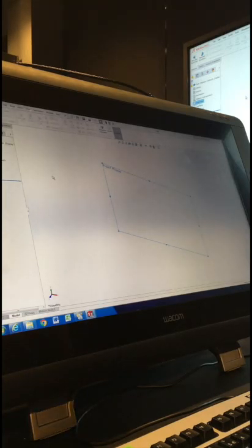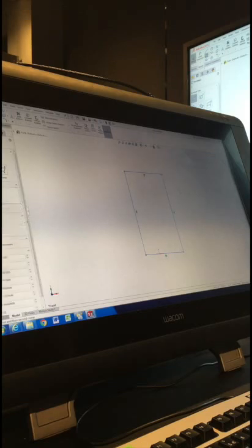So let's start this on the front plane. New sketch, front plane. And this is a new trick, this little one here. I'm going to start a rectangle. I'm not starting the corner of the rectangle on the origin. Very important: start the corner to the side of the origin and then drag up and over. Make it deliberately bigger on one side and then drop.